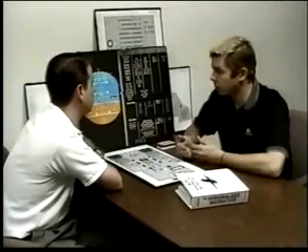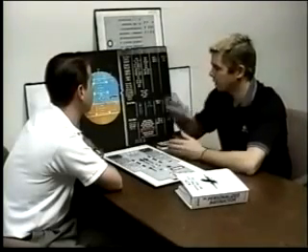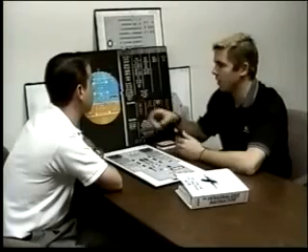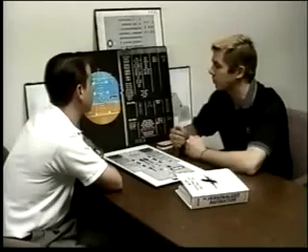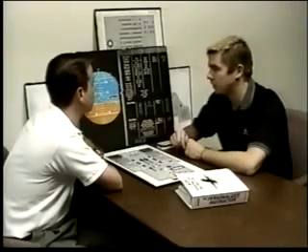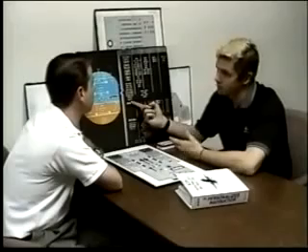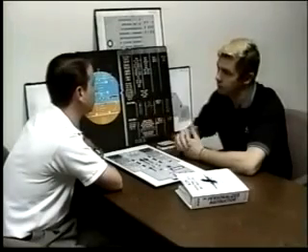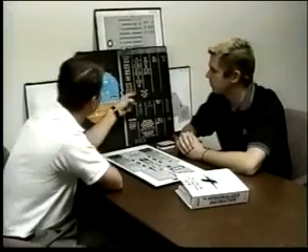And let's just talk normal operations, where I have the thrust levers in the climb detent. Speed gives me a range of thrust anywhere between climb and idle thrust. If I have idle thrust, it's not going to come out thrust idle, it'll still say speed. If I have climb thrust, it's still going to say speed. And it has the ability to give a range of thrust anywhere in there. And Mach is basically the same thing as speed, except in Mach, it's referencing a Mach number. Speed, it's referencing an indicated airspeed.